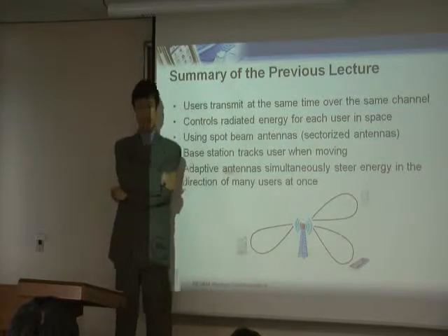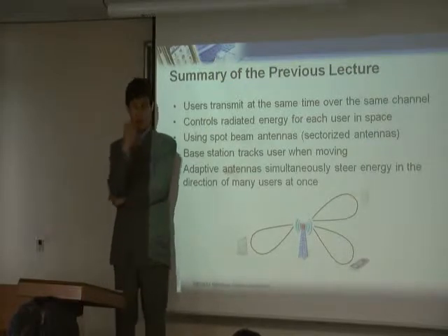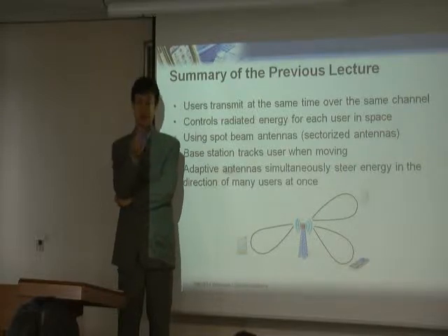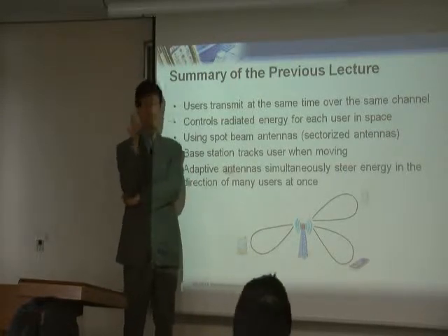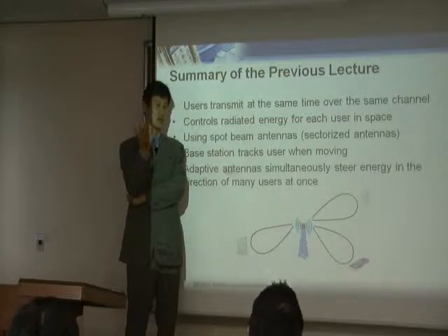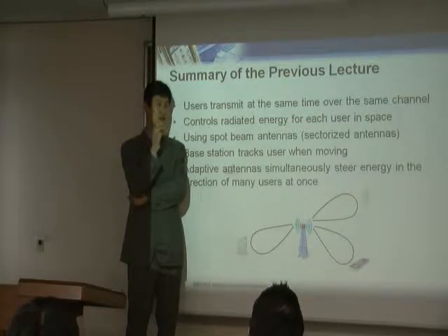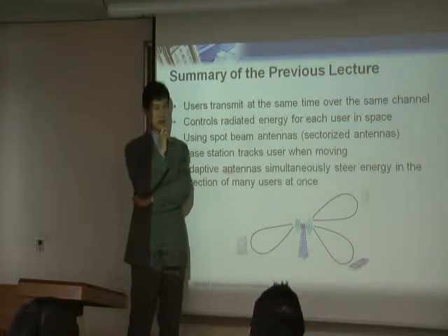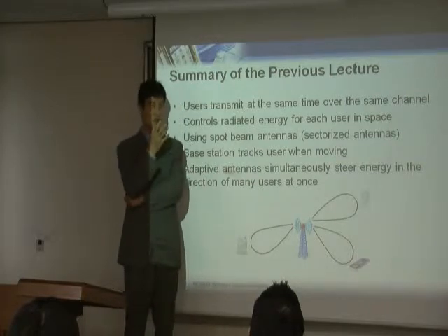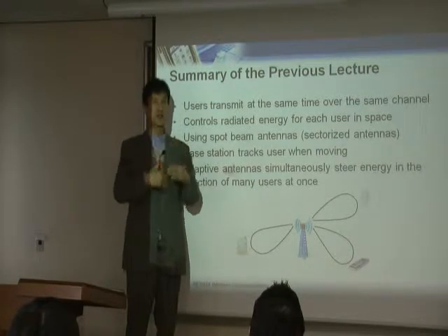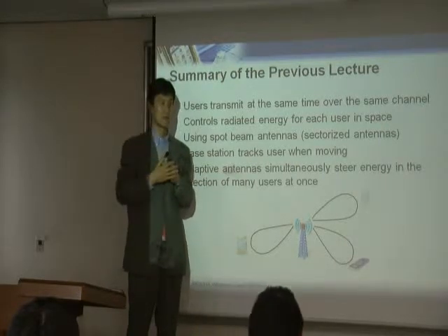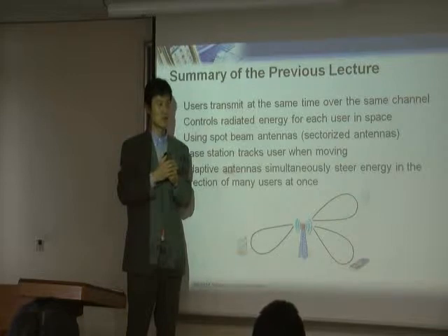So now, let's say you wake up a device. A device is now woken up out of nowhere. The first thing to do is the cell search. When you do the cell search, what you try to do is get the downlink synchronization. You always have to do the downlink synchronization first. In other words, you want to make your downlink timer synchronized with the base station time.